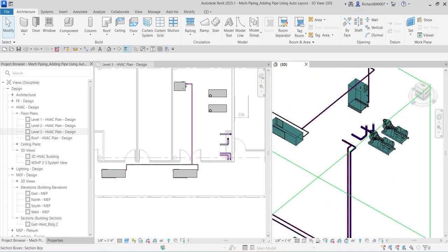Okay, right, so the next thing that we are going to do is physically connect the multi-level water source heat pumps. Remember, previously we added level 1 water source heat pumps to the CHWR system. So next, we are going to physically close the CHWR loop, which propagates throughout the system.